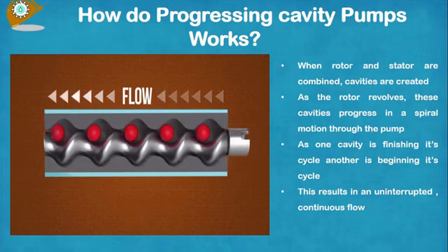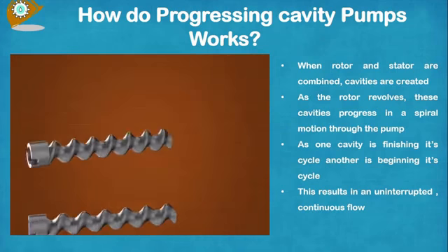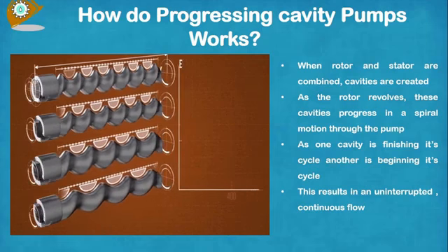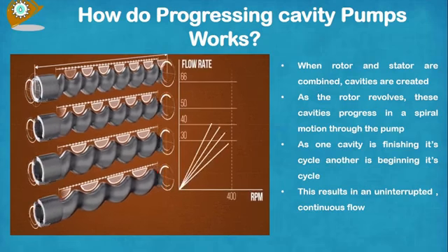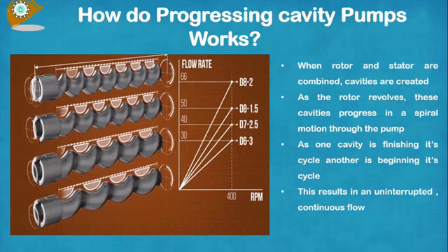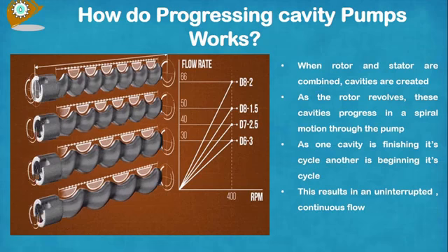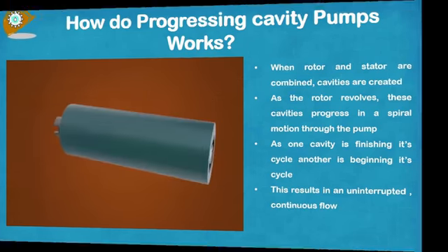An important consideration with progressive cavity pump stators is the geometry profile. Generally, there are 4 different stator geometry technologies in the marketplace. Different flow rate and pressure stability are achieved by varying the design, so choose the right stator depending on the features of the fluid.